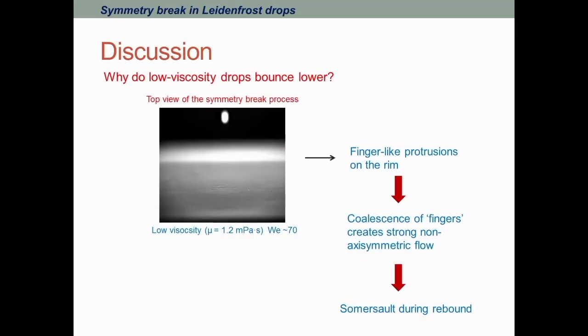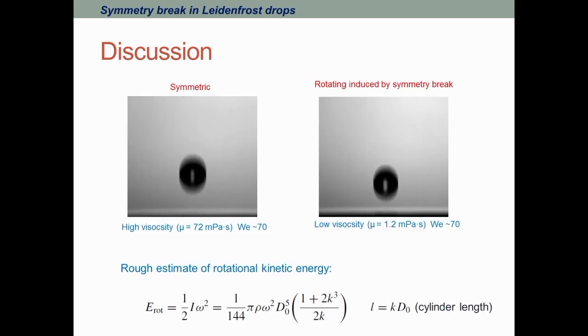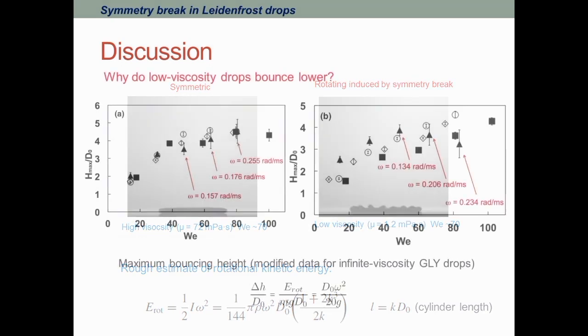No, it's a Newtonian fluid. Both of the videos were for Newtonian fluids. But if you try with shear thinning or viscoelastic fluids, the process is almost similar, because the overall viscosity is very high, so you get a symmetric bounce back. So this is only observed for the low viscosity drops.